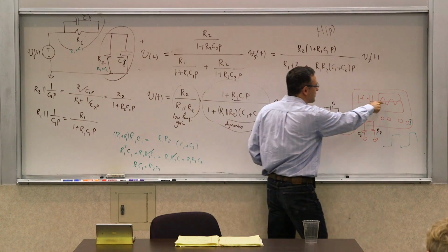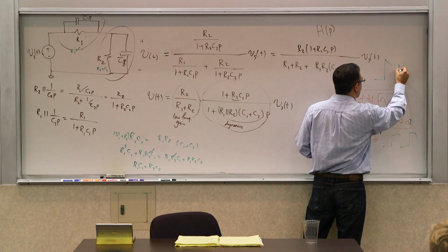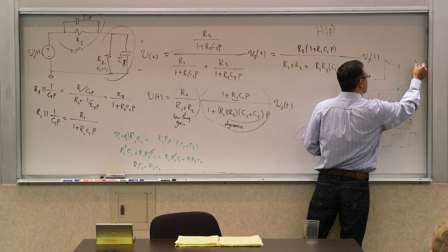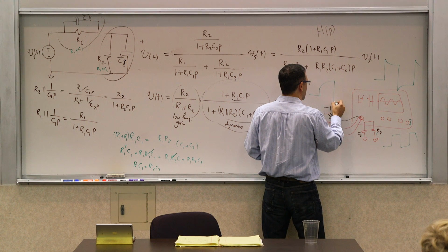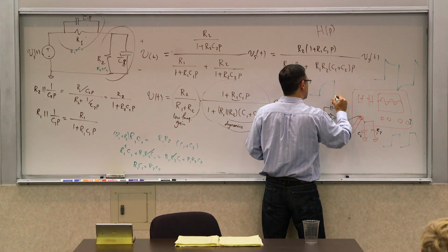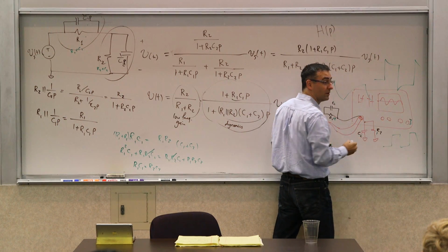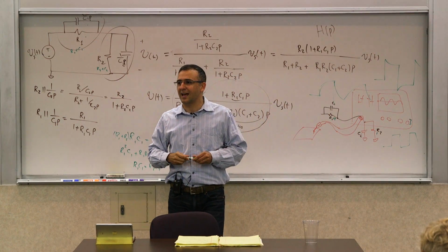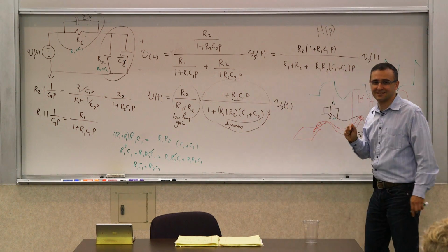On different probes it's different. So when you hook it up to an oscilloscope, you will see a waveform. Now, sometimes when you hook it up, you see something like this. Sometimes when you hook it up, you see something like this. It means that the probe is not calibrated. You play with that knob till you get this square wave.